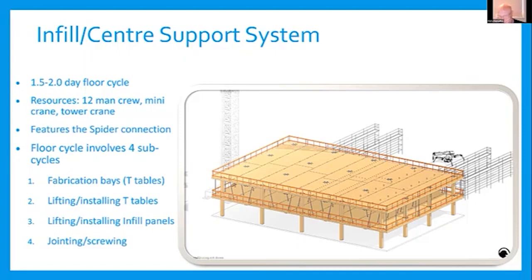We could reorganize this to have a single fabrication bay. The fabrication bays were mainly there to help remove safety issues of putting the spider connector in place in situ, or our lack of the difficulties in creating edge protection. I think you'll see in a moment that the 2 fabrication bays aim to help make sure this spider crane, and indeed the tower crane that you see on the left here, are kept busy.